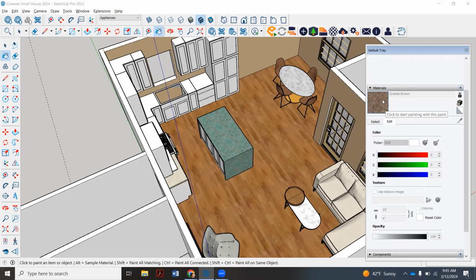And also, if it's transparent, like glass, or if it's something like fabric or texture that's not going to reflect light and instead is going to absorb light. So this will be a bigger issue when we get into photorealistic rendering. But I want you to get into the habit now: when you create a custom material, use something already similar to it as its base. So we're going to do that now.